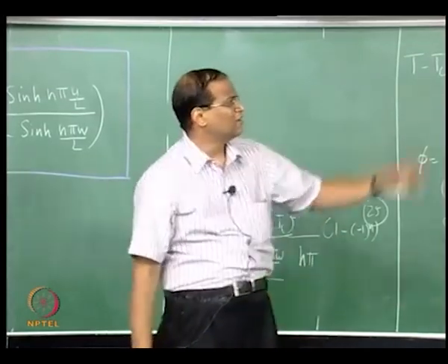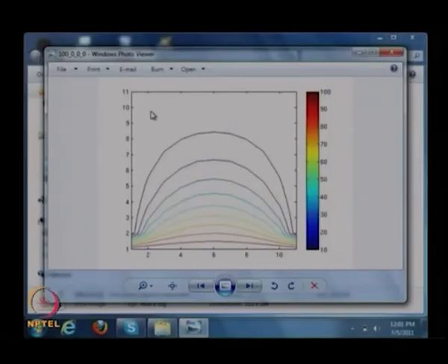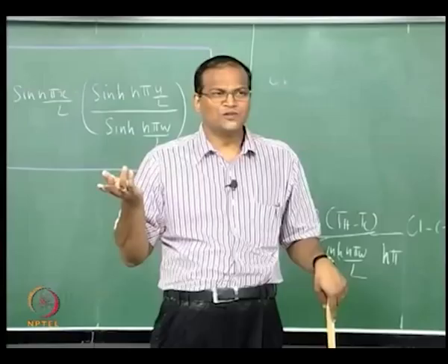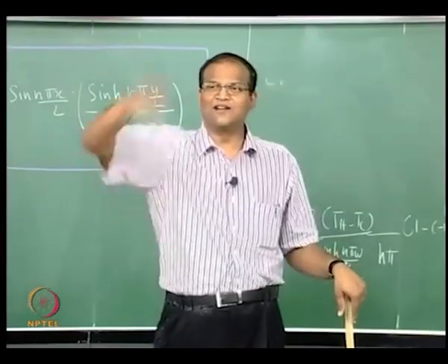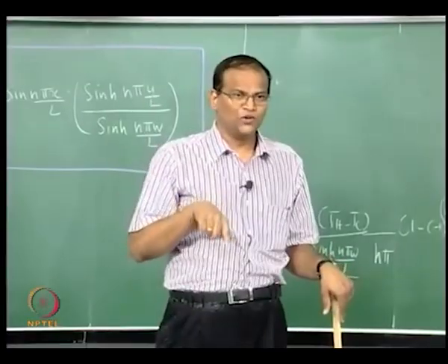Okay, so please look at this graphic. So this gives a solution to the problem, this problem for a square slab which is 10 centimeter by 10 centimeter. As you can see, though this is a problem on steady state conduction, the K is not at all used in the problem, the thermal conductivity will enter the picture if you want to determine the heat flux at the surfaces, where it will be K dT by dx and use Fourier's law.